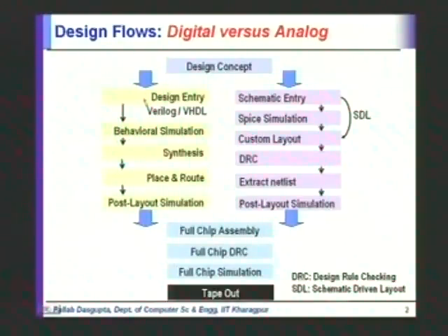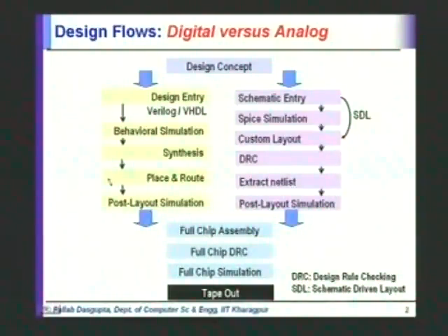And once you are satisfied that the code that I have entered is correct, then you go through the synthesis phase, in which the code is actually translated down into the design having your gates and flip-flops, etc. And then after synthesis, the different blocks, the different modules are placed on the floor of the chip, again in a symbolic way. We still do not have the silicon at this point of time. We just geometrically place the different blocks on the floor of the chip, and then routing means that we have to interconnect these blocks to get the complete chip.